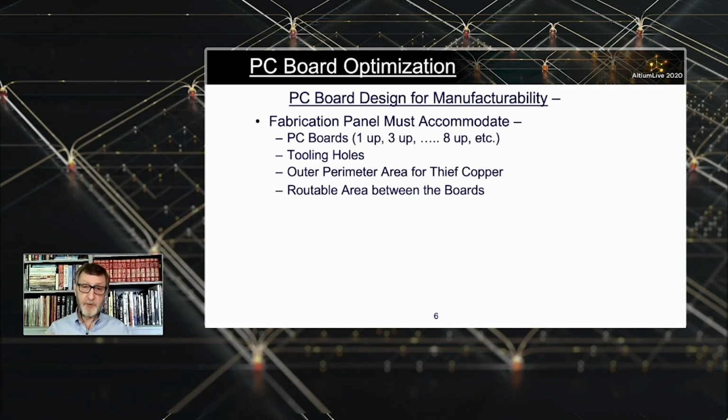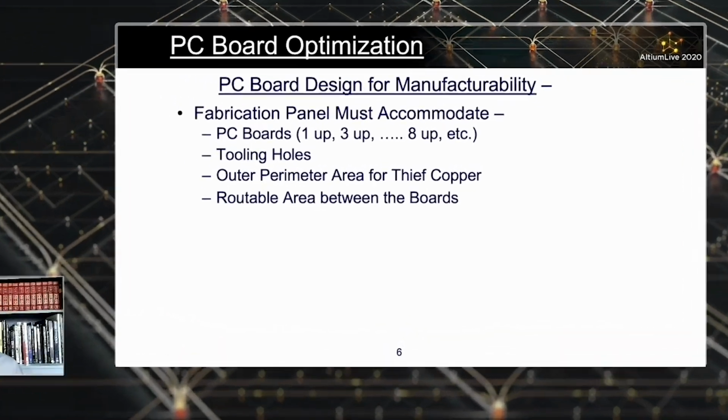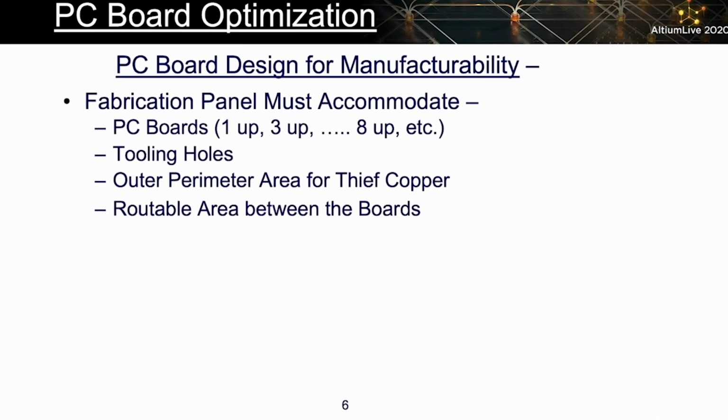The panels get drilled, plated, etched, imaged. These things all happen in different machines. So they have to pick the panel up, move it to another machine, and when they put it down and line it up, it better be nearly perfect. The alignment better be within a few 10,000ths of an inch, or good luck, you're not going to get alignment of these processes. So they have to have very tight, accurate tooling holes in them to be able to move from station to station.